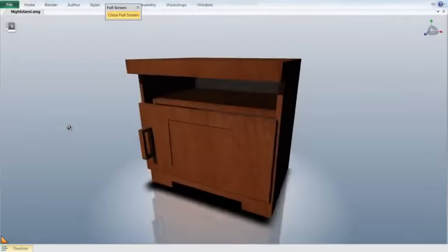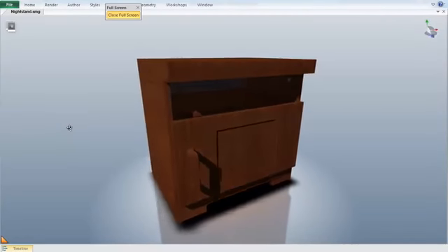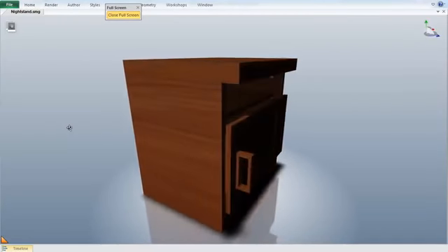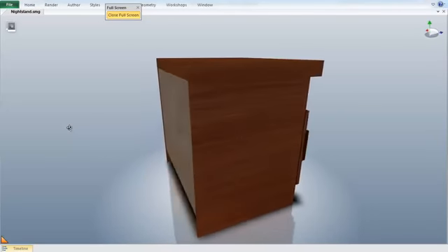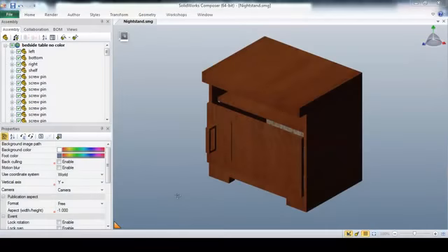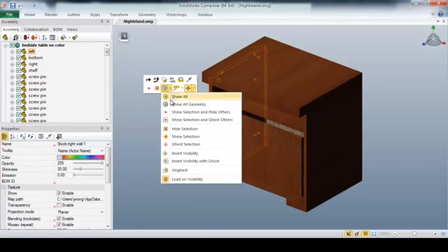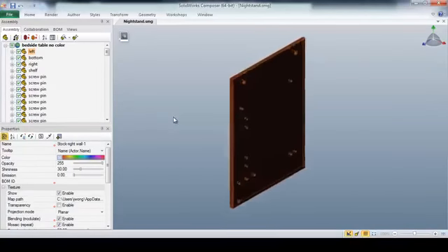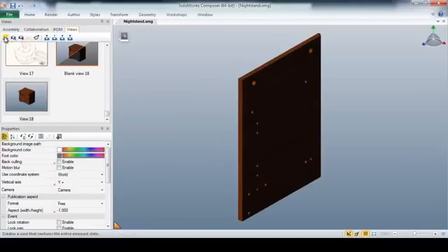Here you can see we have your typical build-it-yourself nightstand. One of the most frustrating parts for the end user with these types of products is how unclear and difficult to understand the instructions can be. But with Composer, we can create visual, interactive, and intuitive instructions. First, I'll quickly create views to represent each step of the assembly process for the nightstand. I'll simply select the first part I wish to illustrate, hide all the other actors, select the Views tab, and create a new view. Like that, we've got the first step of our assembly process.